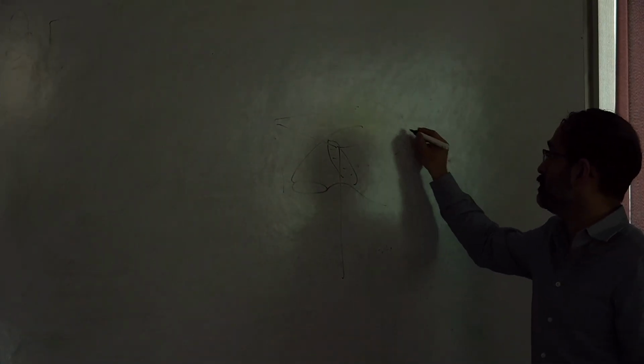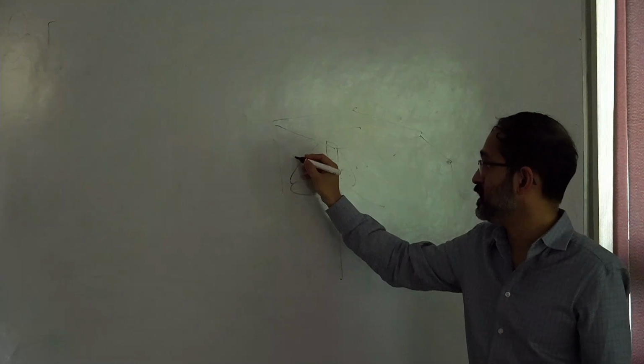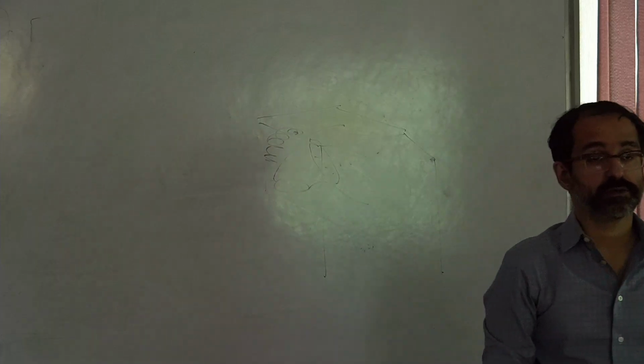If you remember the 3D print that I shared with you, I built an external structure like this, and then we meshed just this part so that the 3D printer would know what part would be solid and what part would be hollow. Okay? And we are building the elements, of course, in the hollow region because that's where you are modeling the fluid flow through, right?